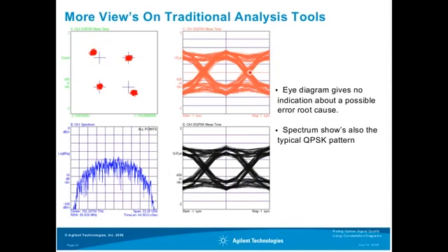In contrast, you see here the phase error of this signal, which is close to 0, with just some noisy deviations. This is the same transmitter, just using an external cavity laser with a line width of, for example, 100 kilohertz. So you can see the transmitting laser has significant influence on the performance of your transmitted signal.